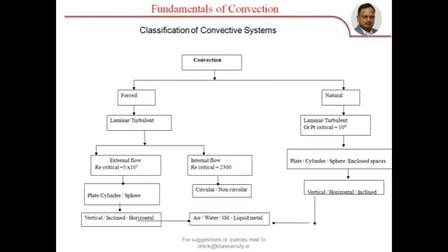So our next step is to apply the continuity equation, momentum equation, and energy equation to a fluid element within the boundary layer. Thereby we will develop certain expressions and we will try to solve those equations to determine the so-called velocity distribution, boundary layer thicknesses, normal boundary layer thicknesses, etc.